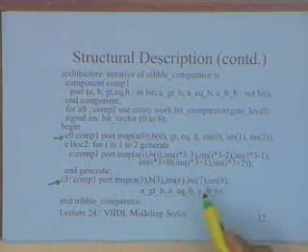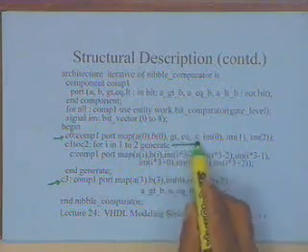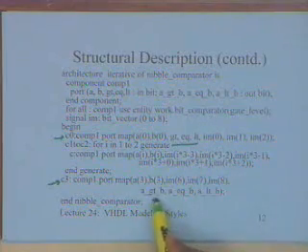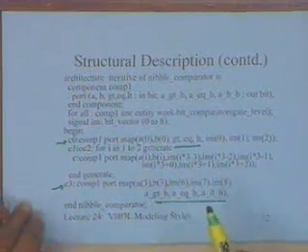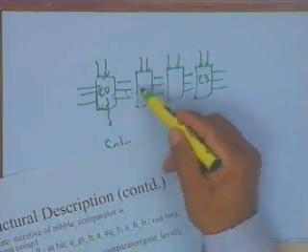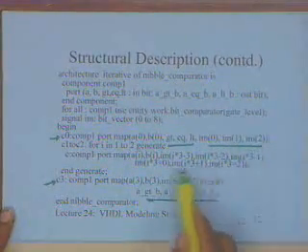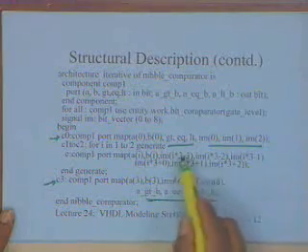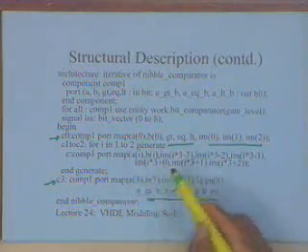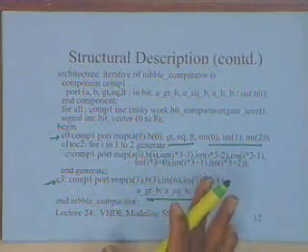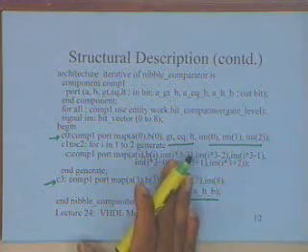C0 and C3 need different statements basically because one is connected to external inputs and one is connected to external outputs. Others are just being connected to these intermediate outputs which are generated from one, and the output of this goes as input of this. So IM0, IM1, IM2 come from the first one, and if you evaluate this, that goes as the input over here, and then the next set comes out. So you can also write this through a generate statement, but all these are structural descriptions. So what we have discussed today is structural descriptions as well as data flow descriptions.